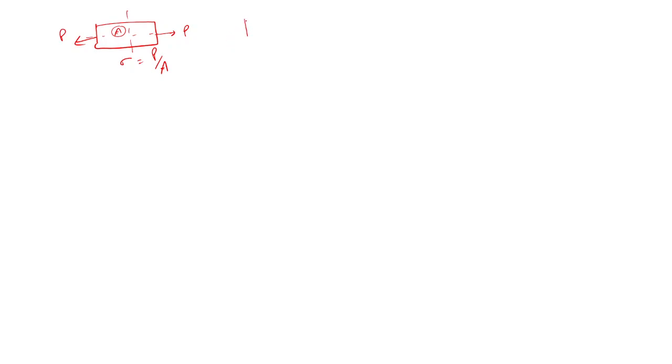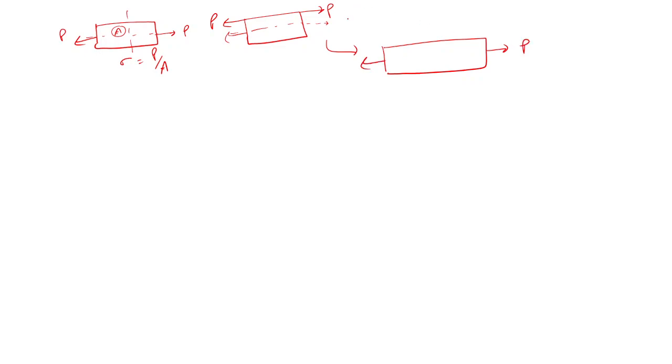Yes, sir. And if the force is not passing through its center line, let's suppose some force is passing from here, first you have to shift that to the center, and apply an equivalent amount of moment. For example, here we will shift this force P to the center, and let's suppose the diameter is d. So what will be the moment due to shifting this force to here? P into d by 2, right? This moment is there.